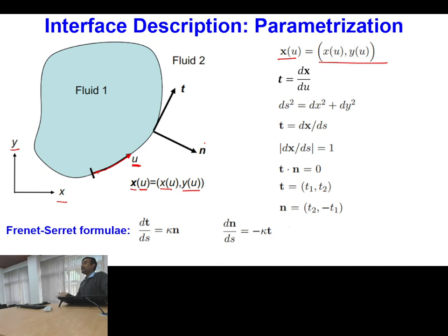Okay, so to define all these forces and the velocities at the interface, which will help us in the evolution of the interface with space and time, we also need to define the directions, the tangential direction and the normal direction to the interface, and the third important parameter which we need to define is the curvature of the interface, because some of the forces which act on the interface are proportional to the mean principal curvature of the interface. What are the forces which are responsible, which are defined using the mean principal curvature?